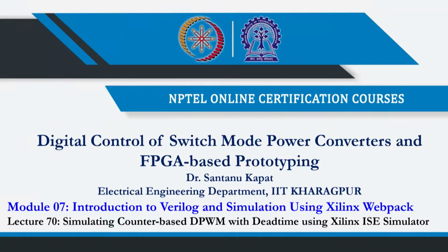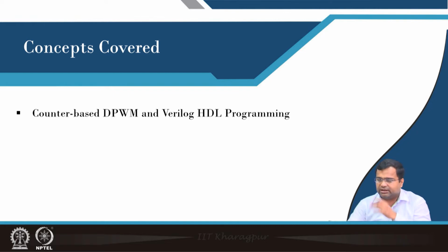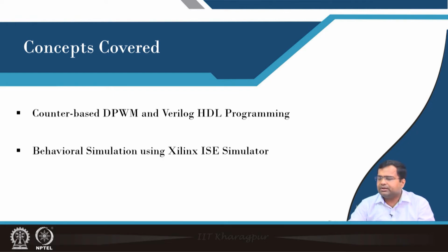Welcome. In this lecture, we are going to discuss the behavioral simulation of counter-based DPWM with dead time using the Xilinx ISE Simulator. This is a continuation of the previous lecture where we discussed in detail the counter-based DPWM and the Verilog-HDL programming. Now we are going to do behavioral simulation and verify the timing parameters.